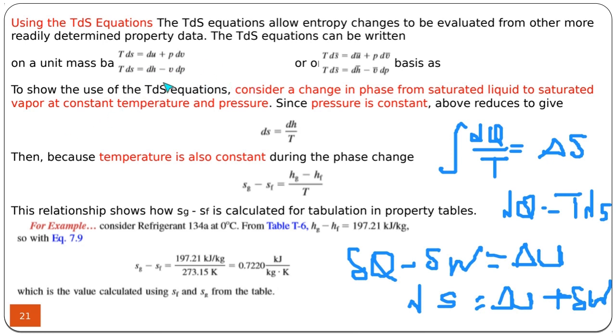by using the relationship between the enthalpy and the pressure work, you can write the same thing as TdS being equal to dH minus VdP. So they are the same things. We do not use the molar basis. So when a property has a bar on it, it's on molar basis, but we do not use it.